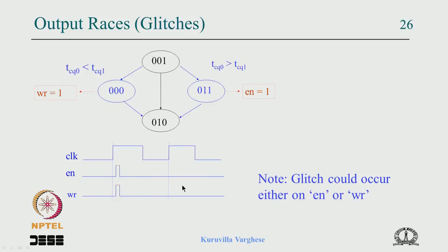So you should keep that in mind, because this is called output racing: these two outputs, Q1 and Q0, are racing each other, and one is faster than the other. That can briefly produce a transitory state, and it can produce output glitches. This may or may not cause a problem, and when there are critical applications we have to worry about it.